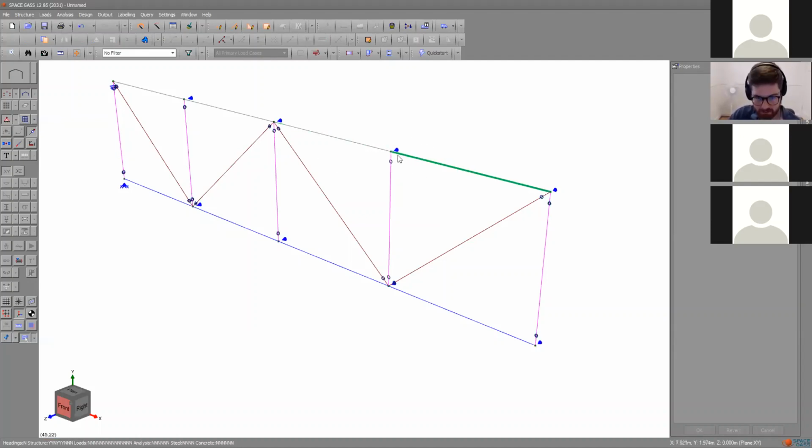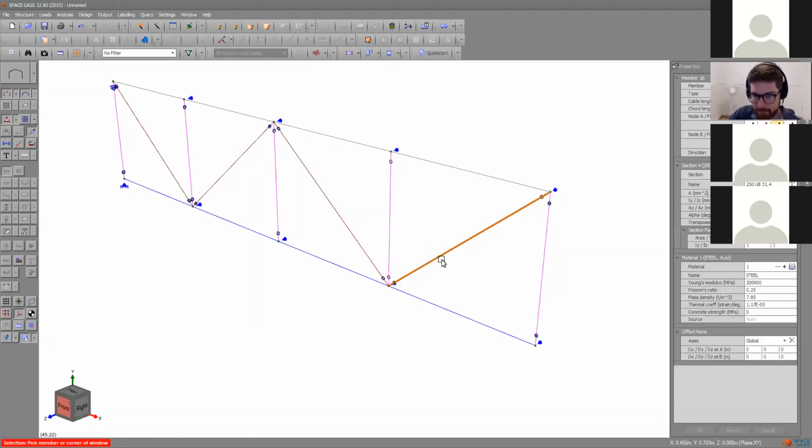You've really got to remove your boundary conditions. But this is still a very common error. Don't fully release the end moments, because you'll have a torsional instability. If you're creating truss elements, just release these two or these two, depending on the axis you're bending about.